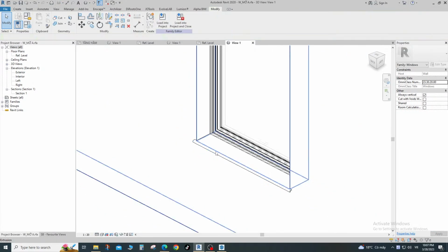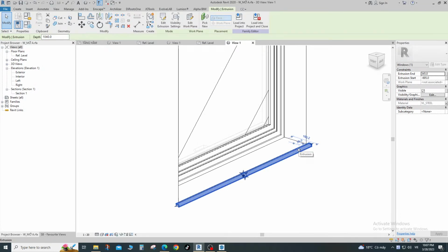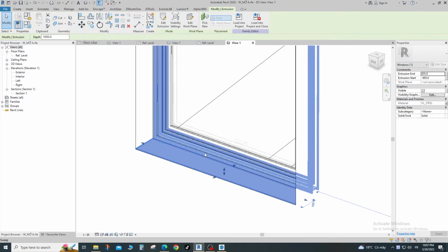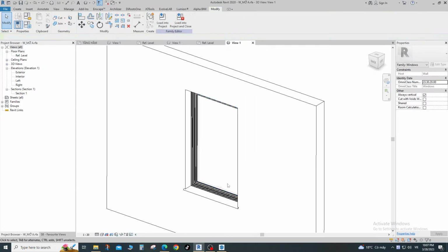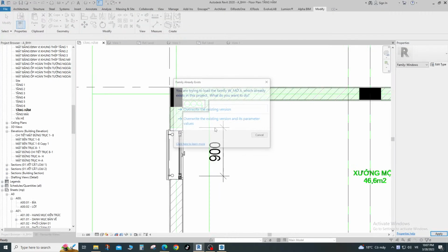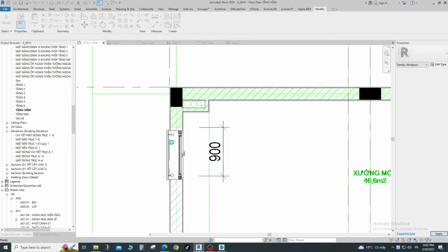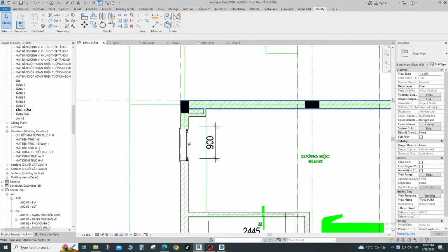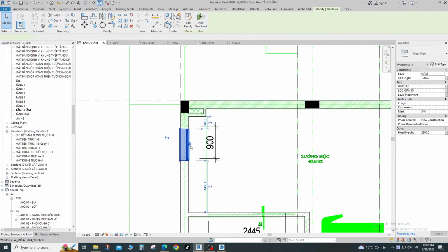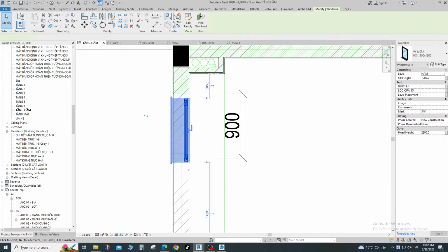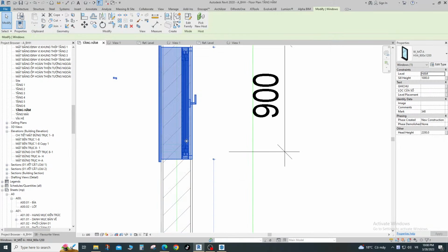Oh yeah, so it looks like we need a little landing here, but we can just go to level 2 and create a little landing using this floor. Okay, so I'll just do this, just something like this. Trim, split SL, split trim TR, and now we have a little landing there. Okay, so this is floor, stairs.